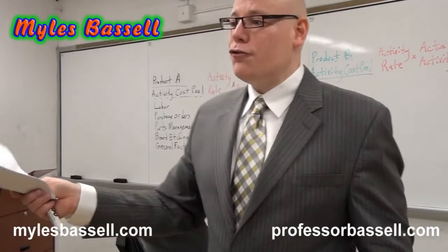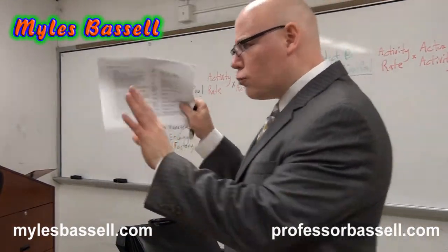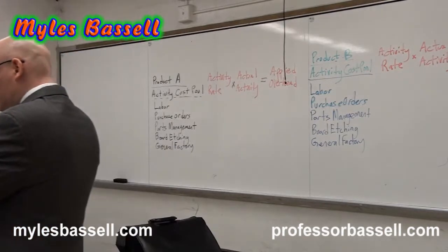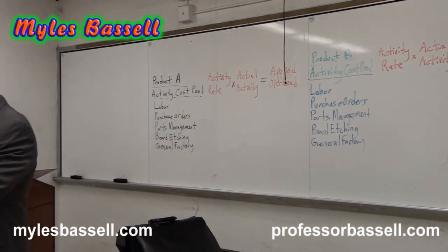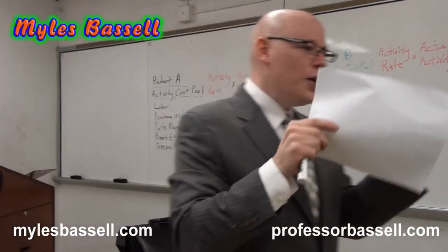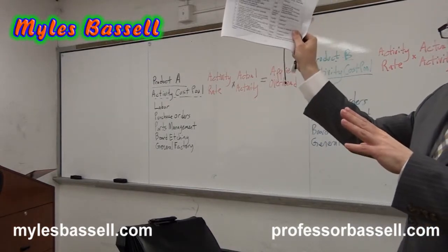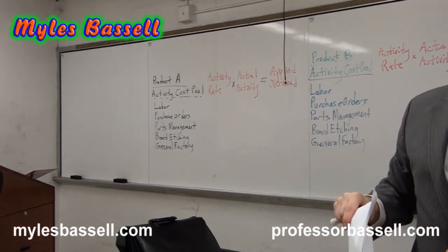Remember, when you go into a factory and you're doing an inspection, don't inspect the ones that Mary tells you to inspect. Right? You need to do a truly random inspection. So if they tell you to check the boxes on top, check the boxes on the bottom.